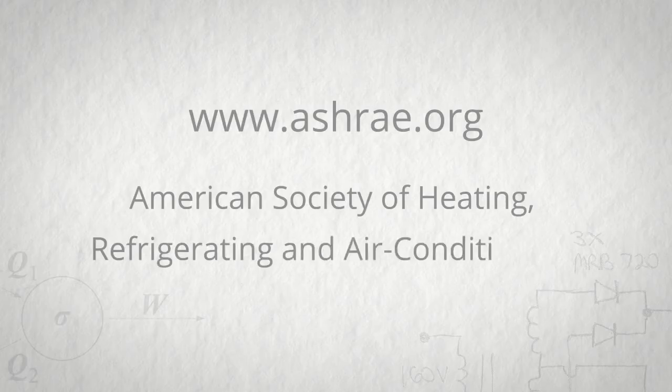Once you manage your airflow properly, the next step in data center efficiency is to increase the temperature of your cold aisle. It's long been believed by many data center operators that the data center has to be cold to keep all the equipment at a temperature that it will run safely at. And in fact, that's just false. If you look at recommended guidelines from ASHRAE, they recommend running all the way up to 80 degrees Fahrenheit. And at Google, that's exactly what we do.